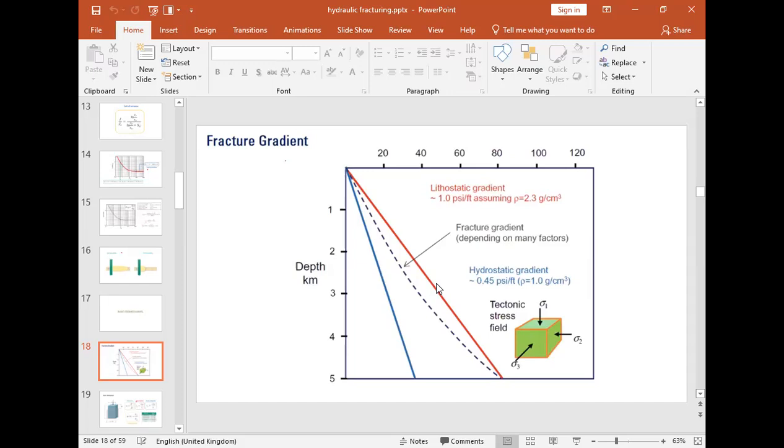So you have to make sure that the mud pressure is greater than the pore pressure and less than the fracture pressure. If the fracture pressure and the pore pressure are not too far away from each other, they bring in the term managed pressure drilling. It is some kind of high-tech drilling that needs high-tech specialists to carry it out.